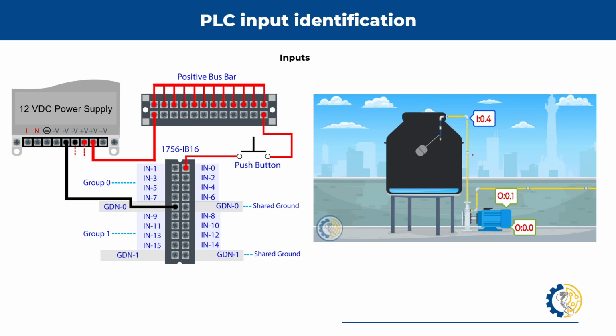Okay? Now, this, where would this be connected? Supposedly a sensor. This is a level sensor. So when it detects a level, the water level, as I'm sure you probably have already seen this, where does this connect to? Which point? It says an input. This is an input. This, for example, is an Allen Bradley module, which we're using as reference. So we ran our drawing here, and it should be connected here to our sensor. Okay?